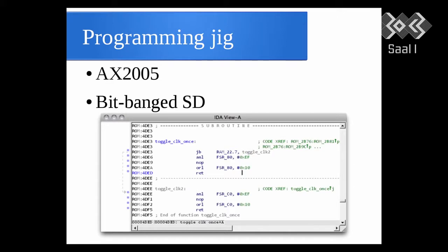This is also 8051 code, and this is a subroutine we found that all it does is it checks for a bit, it turns a line low, waits 1 cycle, turns the line high. Now that is an SD cycle. That's it clocking in an SD bit and then releasing the line high. So that's pretty good. Based on that, we know that it's actually SD.